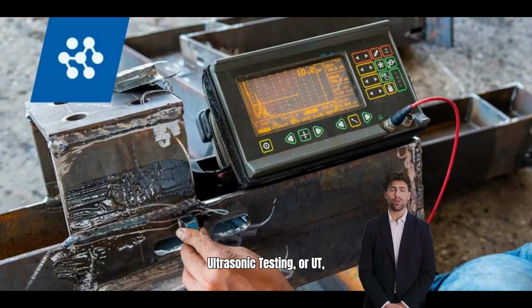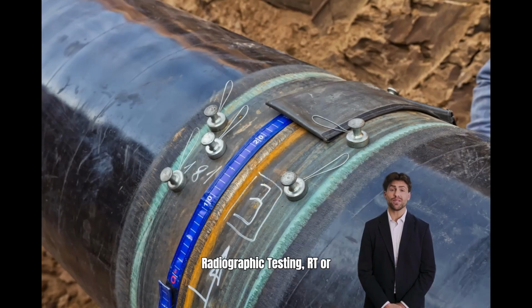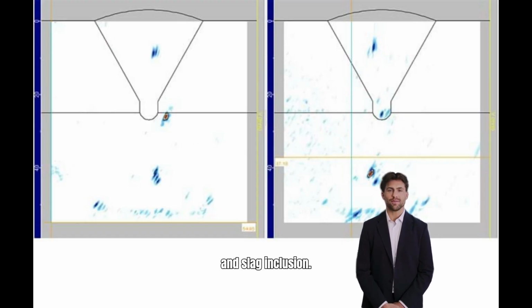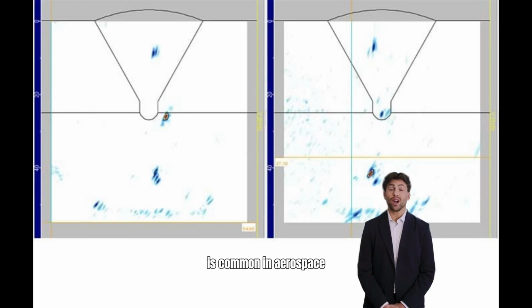Ultrasonic testing, or UT, uses sound waves. When sound hits a defect, echoes return, and the signal shows on a screen. This detects internal cracks, lack of fusion, and inclusions. Radiographic testing, RT or X-ray, uses X-ray or gamma rays. It's used in pressure vessels, pipelines, boilers, and structural welds. This method shows internal defects like porosity, cracks, and slag inclusion. Finally, eddy current testing is common in aerospace and high-precision industries, detecting surface defects in conductive metals.